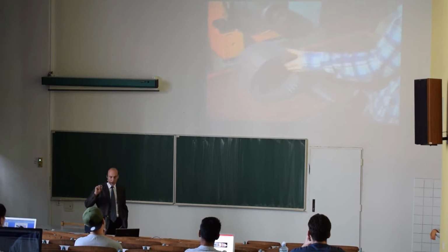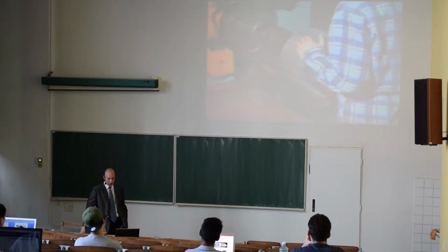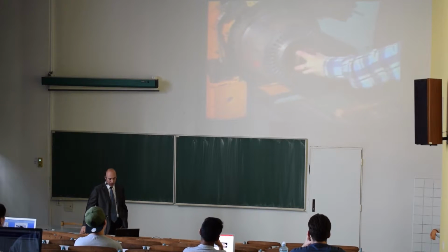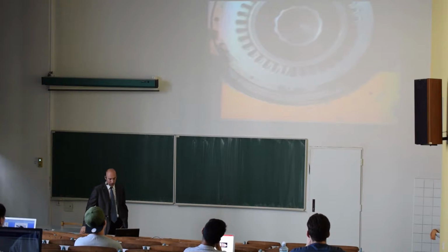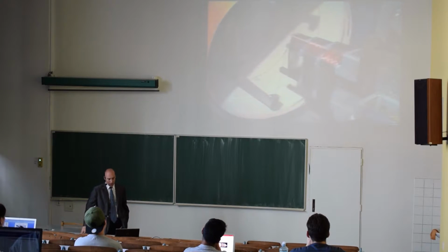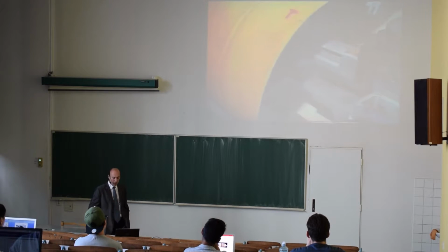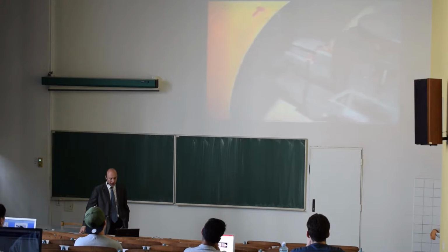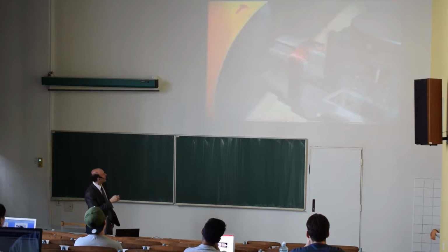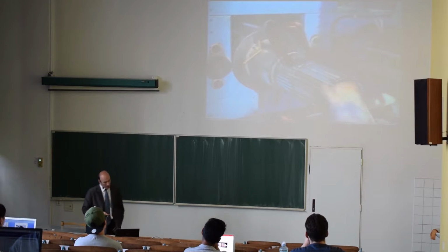Now they will insert insulation into the slots to prevent short circuit between the windings and the iron. So that's the winding. And either it's done automatically or, as we will see later, by hand for some kind of motors. It's a multi-layer winding. So here you see one layer, second layer, and so on.